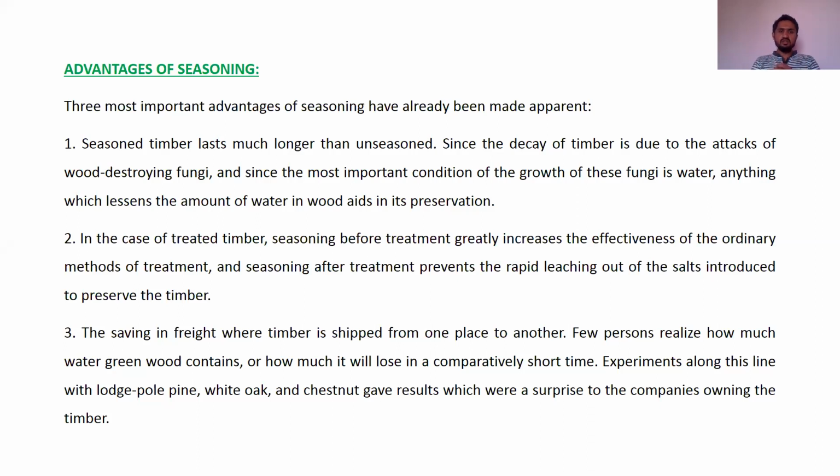So when you are transporting a green timber or a fresh timber, the weight of the timber will be much higher because of the moisture content. Once the timber is seasoned, there will be a reduction in the weight of the timber. If shrinkage happens, it will reduce the volume also, but only to a little extent. Shrinkage is small, but the weight reduction is to a large extent.